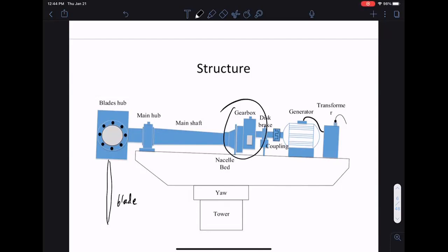So the rotational speed of the turbine sometimes cannot be made constant. Then you have a gearbox, which is tied to a generator. If this is directly tied to the grid, then the generator is 60 hertz. So you have a gearbox that has to do a lot of conversion, and it's just a big, expensive gearbox that tends to go wrong.